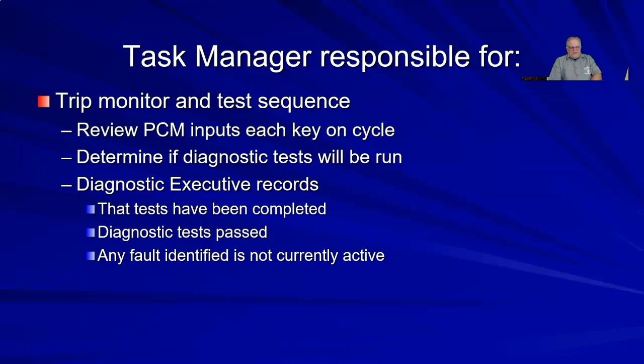Task manager or diagnostic executive is the trip monitor. So what we're looking at on a trip: you go out to the car, you turn the key on, you start it up, you start driving. So it's not just key on, wait a little bit and turn the key off. That's not going to be a trip. It's actually going to require some drive time.